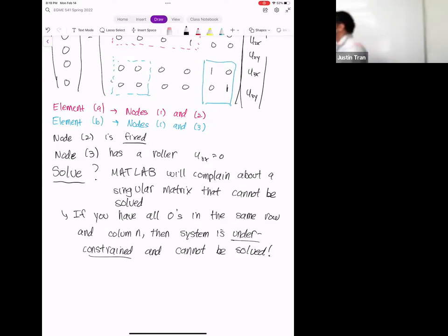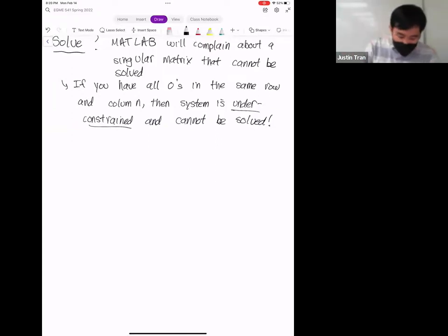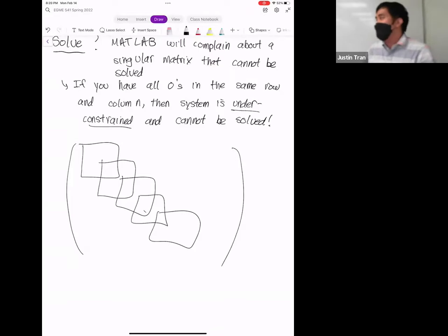I just wanted to double check with you that I started this one correctly. Sure. So I just set up all these stiffness matrices here, for the spring here, and for the bar here, and then again here, and then I'll just combine all this. When you combine it, it makes a nice pattern, because they're all in series. It would look like that basically. But they're all going to overlap on their corners.